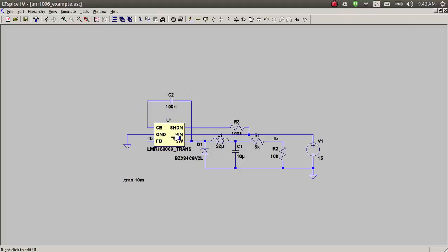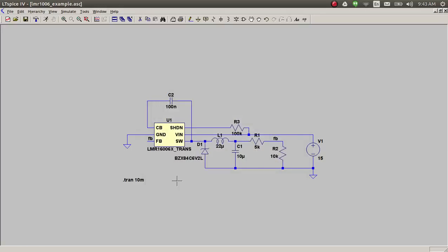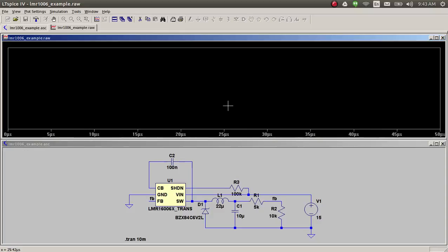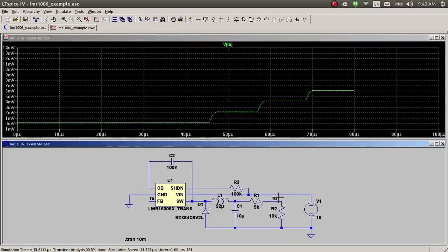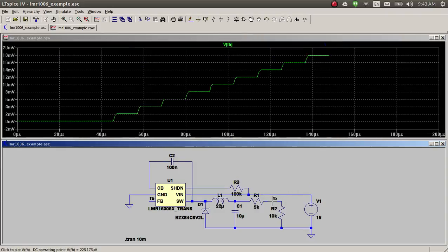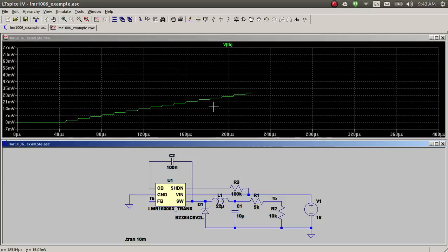Okay, so we have to set that parameter with this cell. That's basically what's happening, and so that's what I've done here. And the spice line, I have just set SS is 0. I needed to make one more correction. I need to put the diode model. And so if I run the simulation, okay, well, that's too much. You can't see much, but I can see that this guy is slowly building up. So this is starting from the initial value of 0.